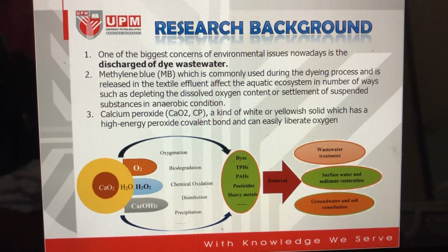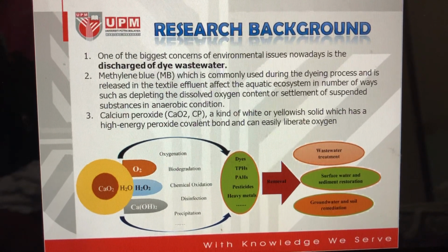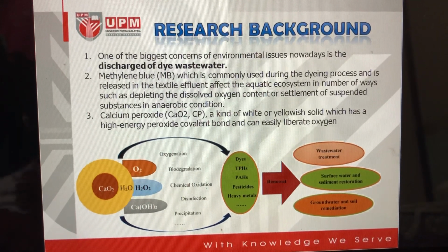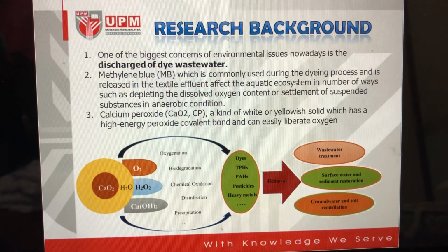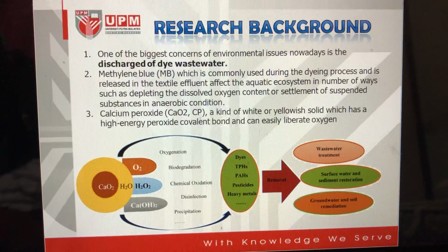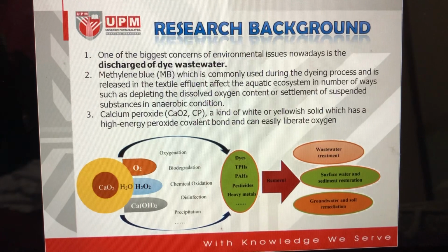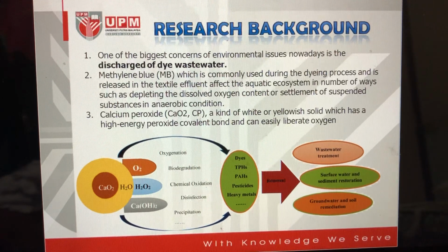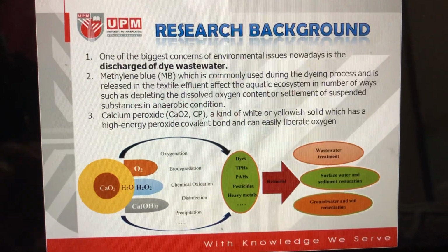Calcium peroxide will react with water to produce hydrogen peroxide and oxygen, as well as Ca(OH)2. The stability of calcium peroxide makes it an effective solid phase to supply hydrogen peroxide and oxygen for aerobic biodegradation and chemical degradation of contaminants in water and soil. Calcium peroxide has exerted great performance in removal of dyes, chlorinated hydrocarbons, petroleum hydrocarbons, pesticides, heavy metals, and various other contaminants.